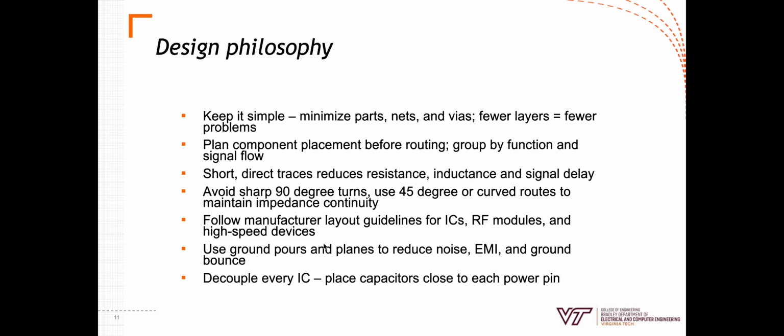This is common with buck converters or boost converters, where they want the boost capacitor to be very close to the boost pin to minimize impedance, and to keep noise out of that specific pin and keep your power quality as high as possible.